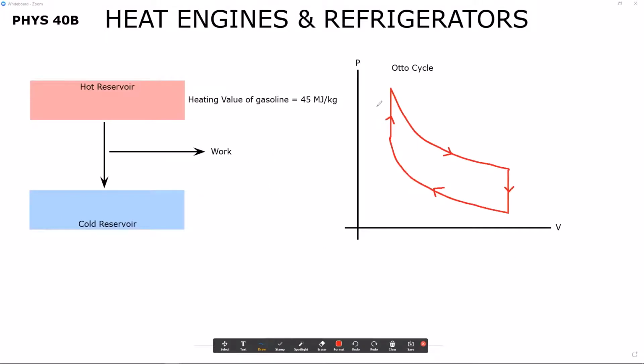And that cycle is shown here in the Otto cycle. This is a pretty basic cycle for a car engine. And what this does is it shows that in these two adiabatic processes, work is being done. Under this one, this is where your compression is done. So we're using the engine's power to compress the gas, and therefore we're using power, and we're adding energy into the gas inside of the cylinder, rather. And then at this top adiabatic process, this is where the combustion occurs, and that's where we get more energy back out. So we have a net work done by the gas in this case, and the area inside the cycle is what we get out of it. So that's pretty simple, right?